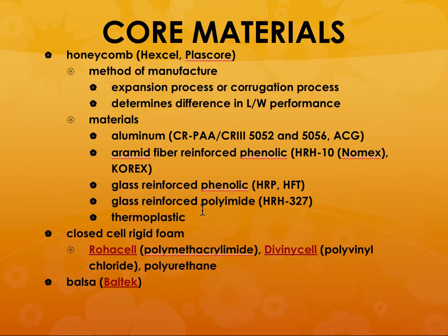Or you can go one step crazier. It's called balsa, one of the lowest density wood type of materials. So balsa wood is extremely lightweight. For example, some of the UAVs have the whole wing structure made out of balsa wood. You just put a very thin sheet of composite material to give it the strength required, but still the light weight is obtained by having the core material made out of balsa.